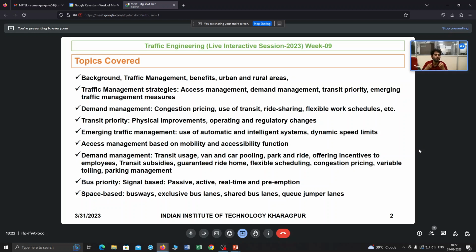It is also a traffic management strategy, because if you are reducing your one-way or two-way travel time, then you are using your resources effectively. As an example, suppose you have 10 buses. Your planned time is that every 10 minutes a bus will reach from A to B, and then B to A it will take another 10 minutes, and 5 minutes is layover. So ideally within 25 minutes it should do one round trip. Suppose you have planned that one vehicle will do three round trips per day.